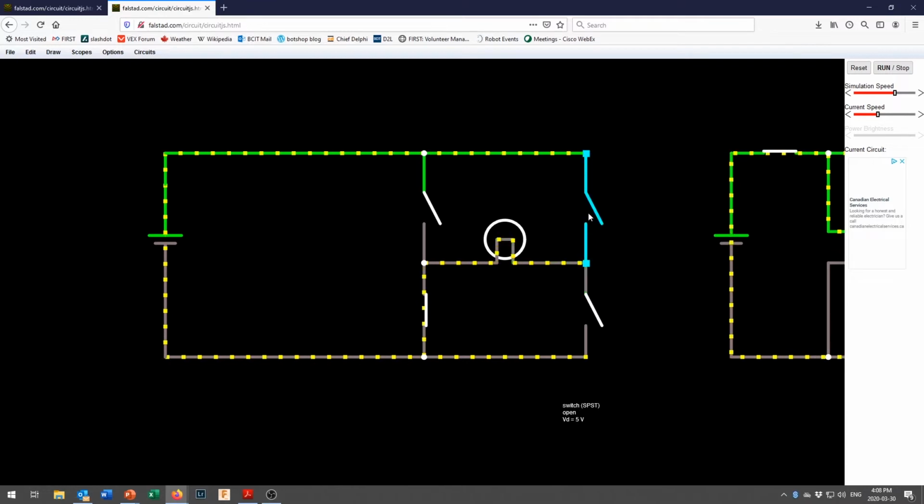And again, if we turn the switch on and off fast enough, we can control the speed fairly smoothly, the average speed that the motor is putting out. And we can get that average so smooth that nobody notices that we're actually flicking a switch on and off really fast. So one direction, off, other direction is how we can control those motors.